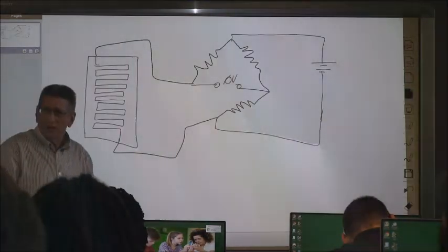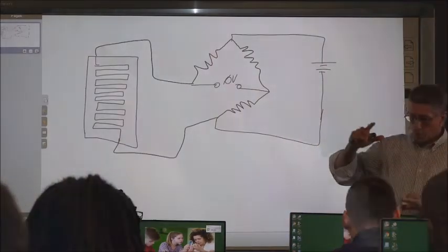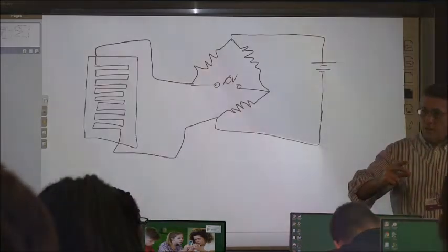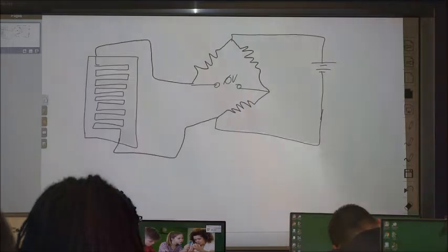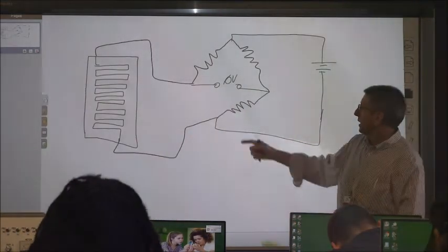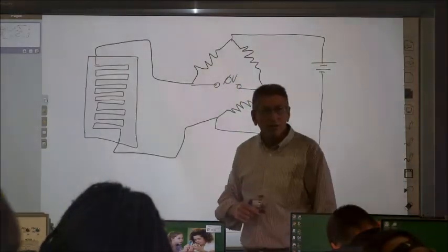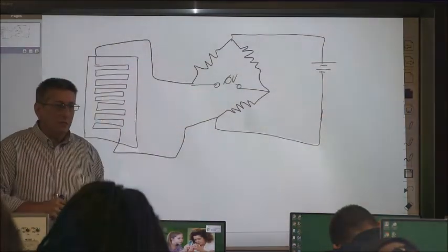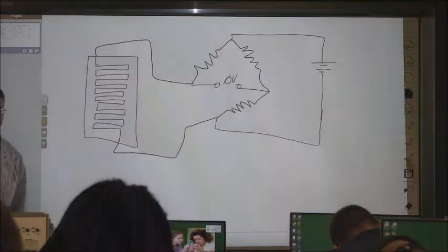Yeah, kind of, yeah. We checked a lot of different stuff, like the force on the push rods inside of an engine, or the amount of torque on a crankshaft or camshaft. The physical force load. Yeah, that's right. So as this thing twists and flexes, obviously the voltage output here is going to change, right? And depending on this voltage, you can equate it to some kind of strain or stress or load that's being applied.